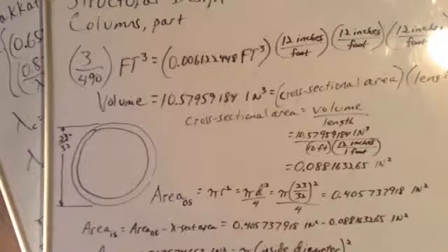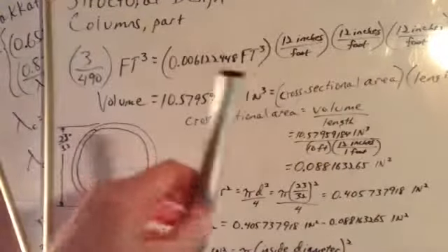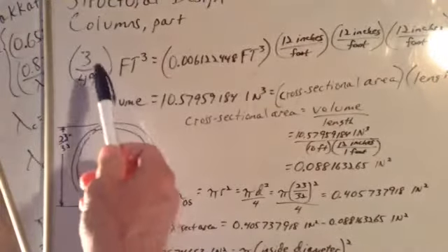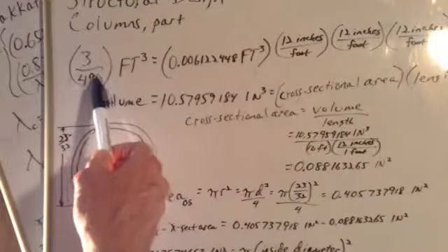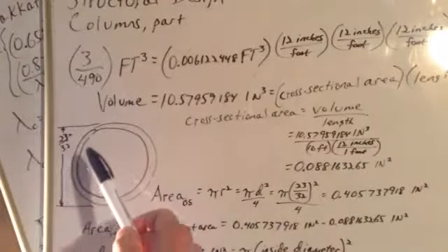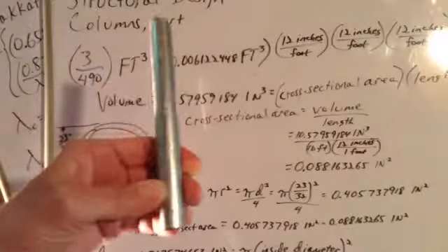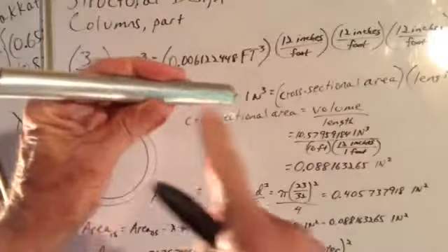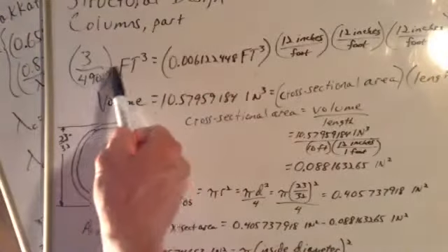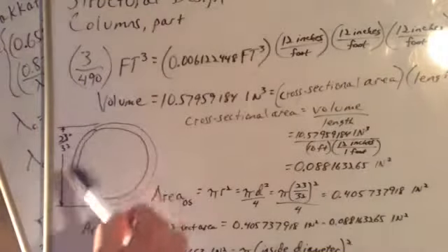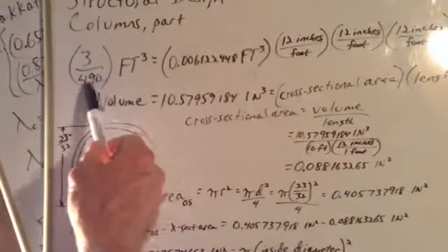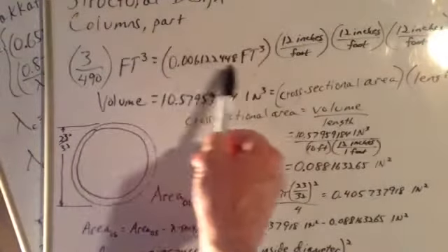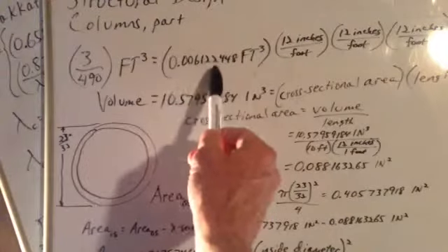Okay, a 10-foot section of this pipe, this 1/2 inch electrical conduit, weighs 3 pounds. A cubic foot of steel weighs 490 pounds. So 10 feet of this, the cross-sectional area times 10 feet of length, is equal to that many cubic feet, because it weighs 3 pounds and 1 cubic foot weighs 490 pounds.